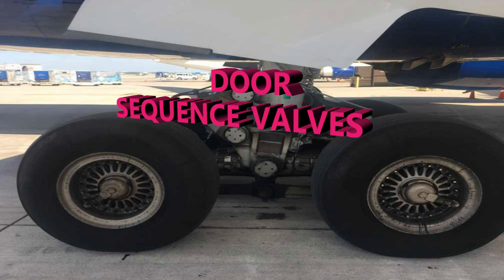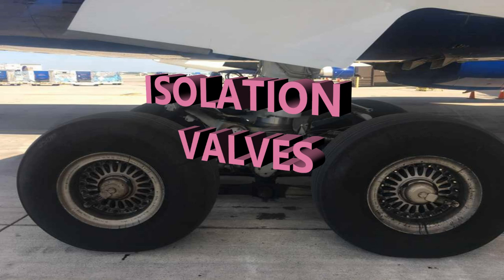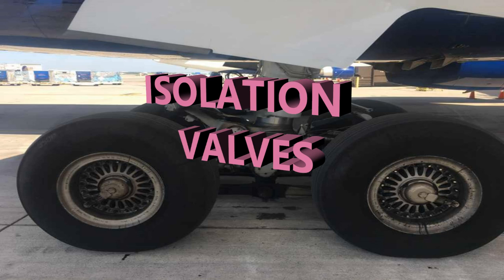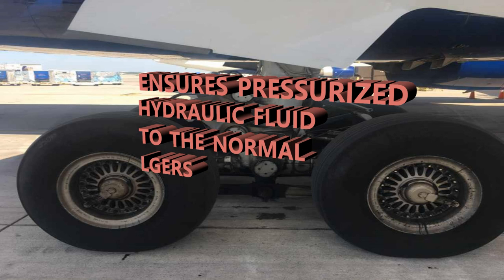So remember, two manifolds, one for main landing gear, one for nose landing gear, and then you have the isolation valves. We're going to talk about them a little bit. Now, the isolation valves are there for what purpose? Okay, they're going to make sure that there's pressurized hydraulic fluid, right, for the normal operation of the extension and retraction of the gear.